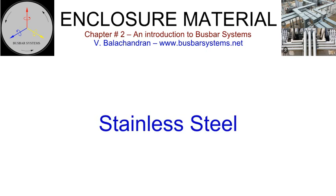Stainless steel. There are some extremely corrosive atmospheres where clients prefer stainless steel for bus enclosures. Chlorine and saline atmospheres aggressively corrode steel and aluminium enclosures. Stainless steel is the preferred material in offshore platforms and chlorination plants.